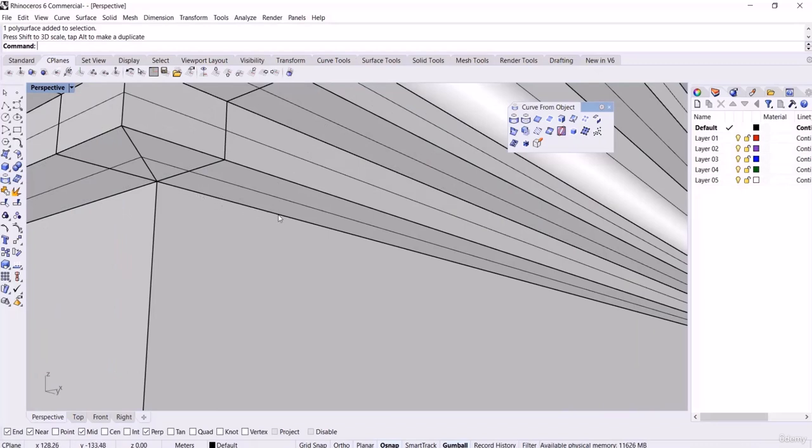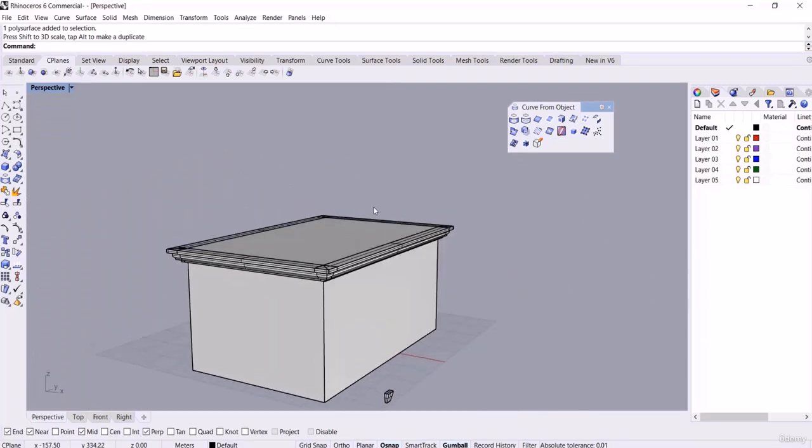So here you may want to select these edges and consider them as the path. As you can see, we got some edges and you may want to specify them as the path of the IsoCurve. Let us give it a try. We should select the objects to array. Here it is. Press enter. Then I should select the path curve.